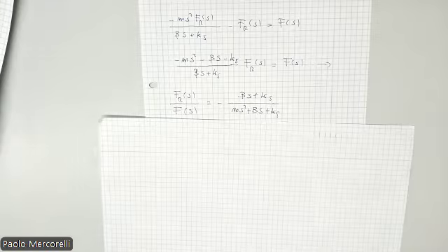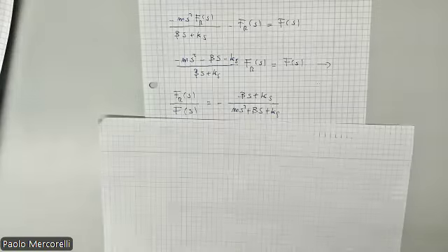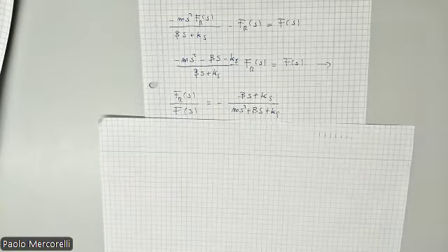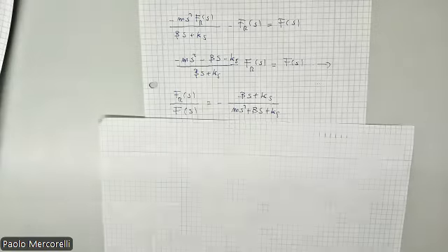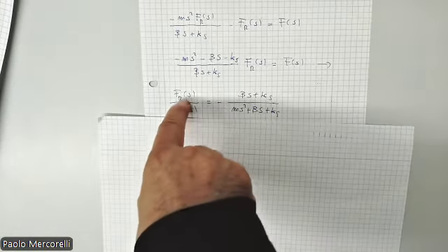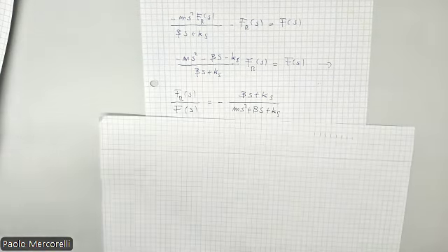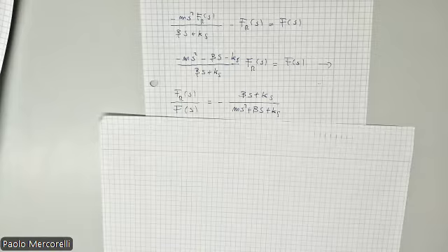If you think about it a bit at home, you now have the possibility to write the transfer function directly. If you do some exercises on electrical and mechanical systems, it's not so difficult, because we defined the reaction force as a linear combination of the effects of the velocity through beta and the position through ks.